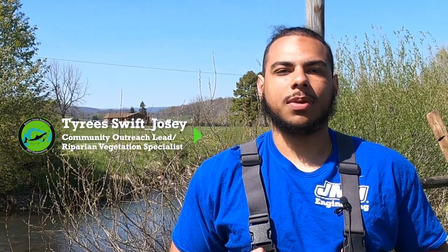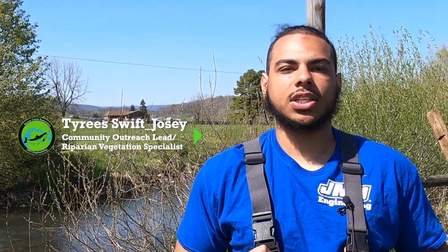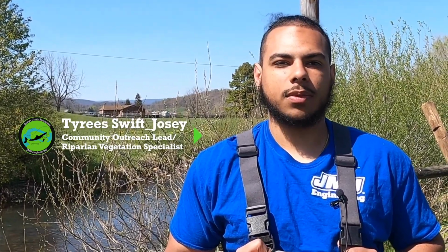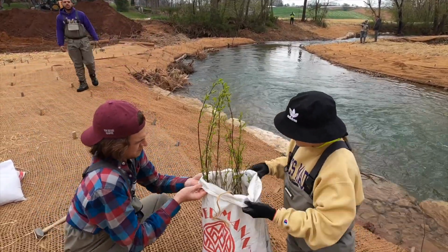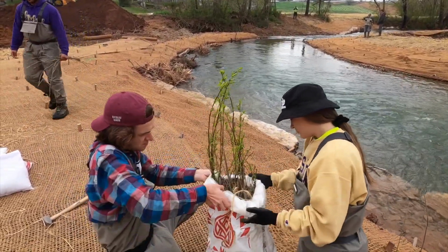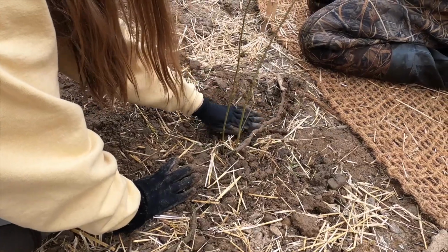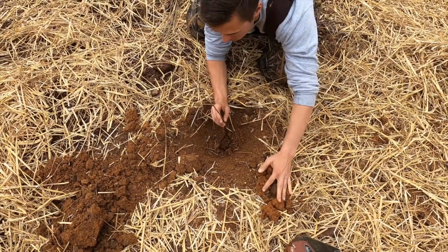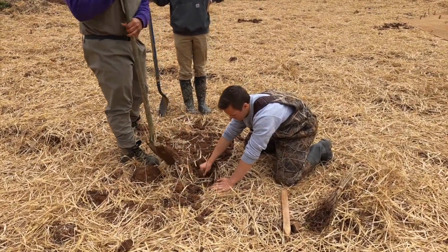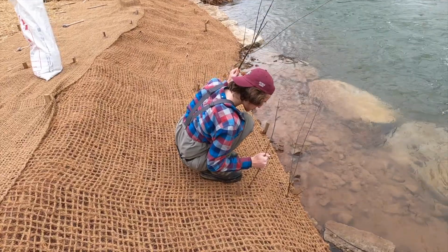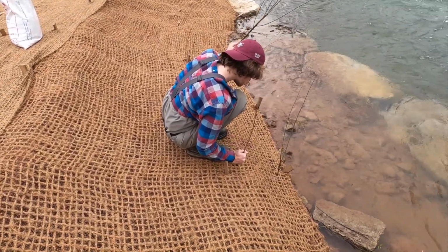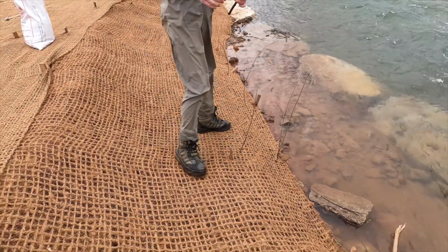The Beaver Creek team implemented riparian vegetation on the left and right side of the bank. On the closest side of the water line, there would be an integral implementation of riparian plants of black willow, river locust, and river birch. On the back end of the side, 10 feet away from it, the bur oak would be implemented. With these implementations, it will help stabilize the stream banks and help prevent flooding and erosion on the sides.